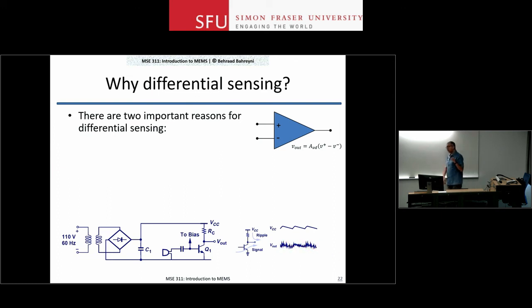variation. And you might have heard this in poorly designed audio amplifiers, that all of a sudden you start hearing the 60 hertz or 120 hertz. It's usually a low frequency signal that your ear picks up. The solution to that is to improve your power supply or figure out a way to do a differential measurement. Now, what I want to do is I want to go and produce a signal or look at a way to subtract this common interference from this signal so that I get my audio signal out only.